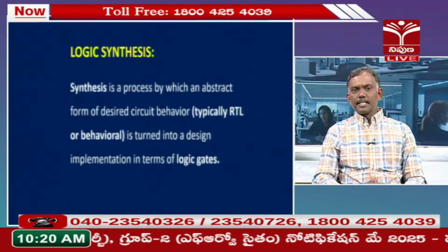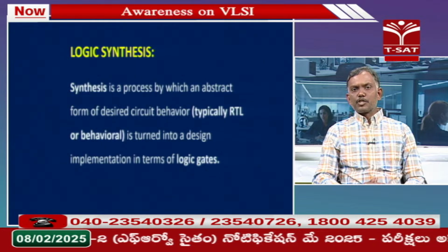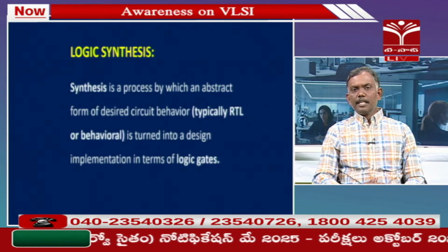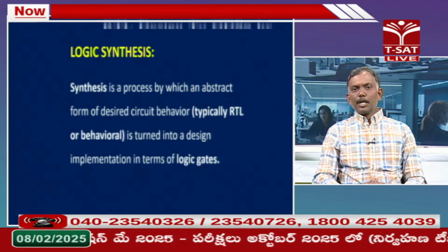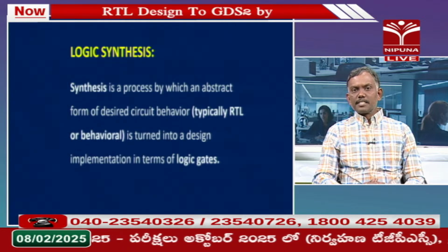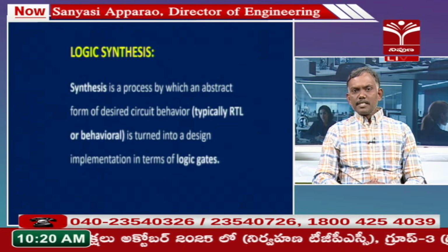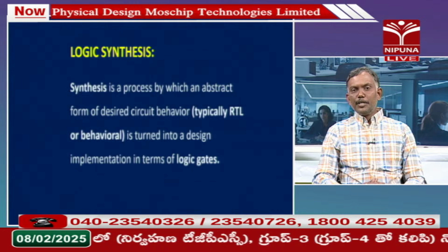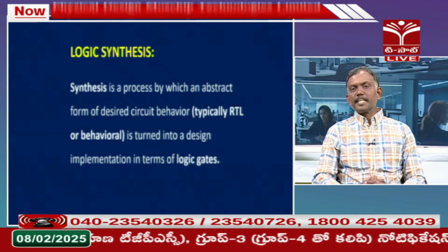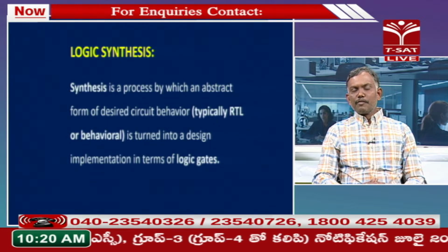Now coming to our logic synthesis. If you recollect the ASIC design methodology, in the first part we completed front end design, and the output is RTL code, Verilog or VHDL. The next stage is logic synthesis. Logic synthesis is the process of converting our RTL into logic gates, digital gates, a conversion of this code.